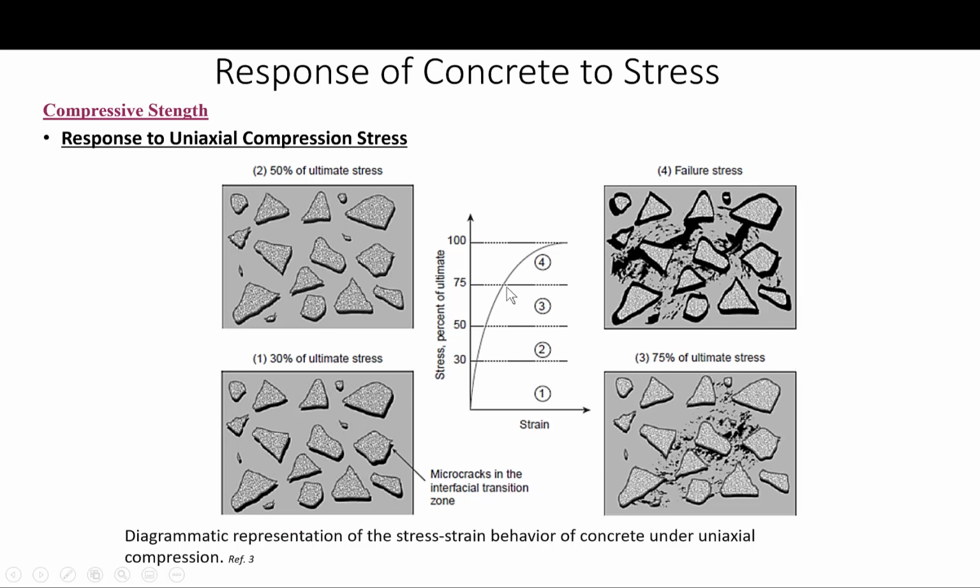All right. At about 75 to 80% of the ultimate load, the rate of strain energy release seems to reach the critical level necessary for spontaneous crack growth under sustained stress, and the material basically strains to failure, as happens here. All right.